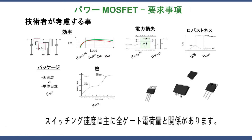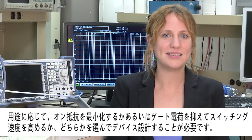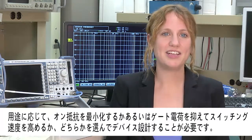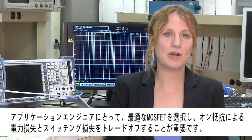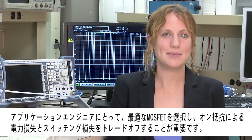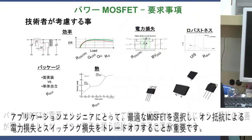Switching speed correlates to the total gate charge that needs to be charged or discharged in the gate drive circuit, QG. It is critical to choose whether you need to minimize the on resistance or to accommodate fast switching speed by keeping the gate charge under control when designing a MOSFET. For the development engineer of the application, it is important to choose the optimum MOSFET and trade off on resistance power loss versus switching power loss for the given application.